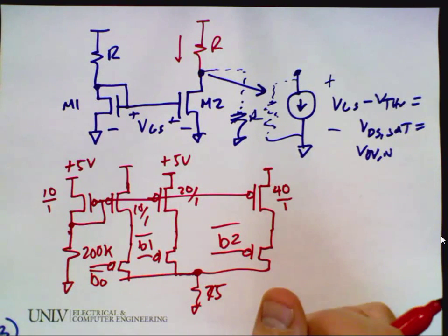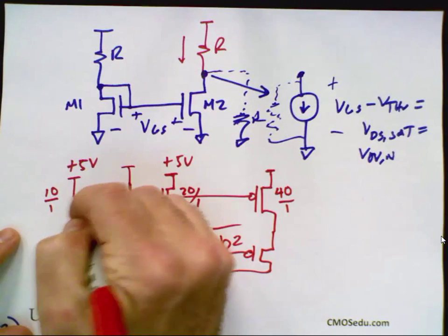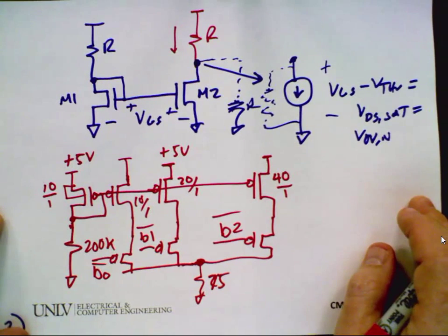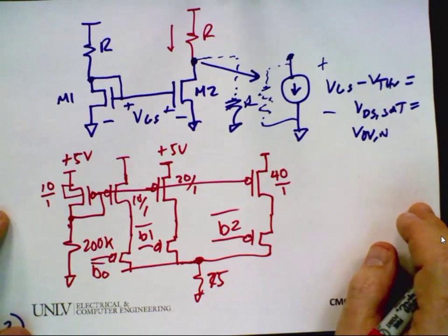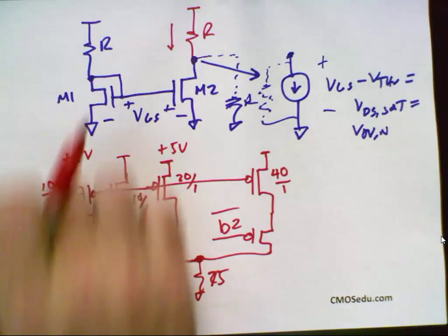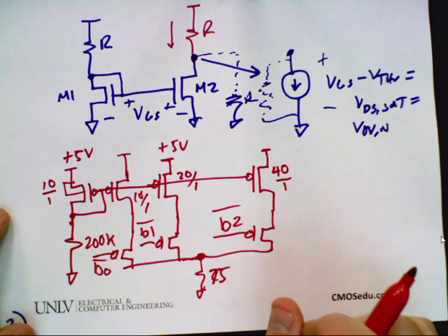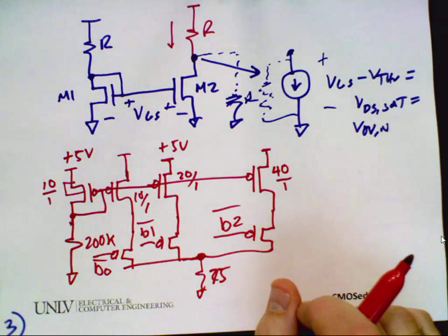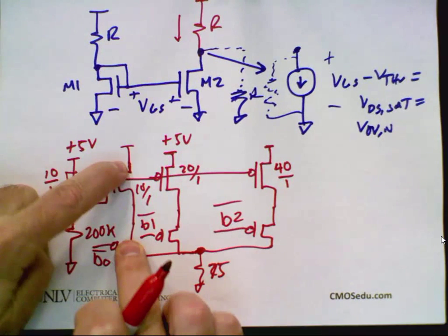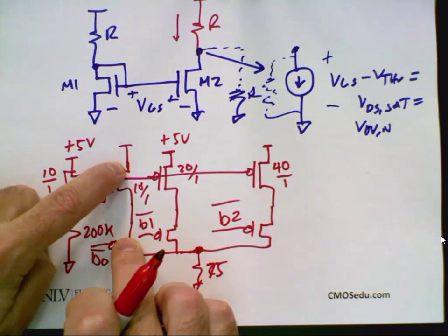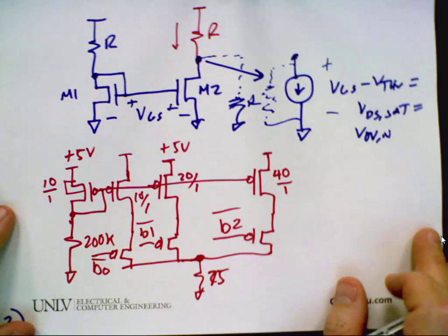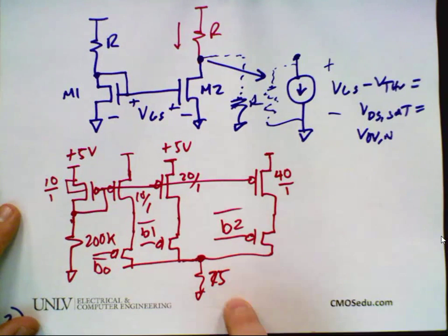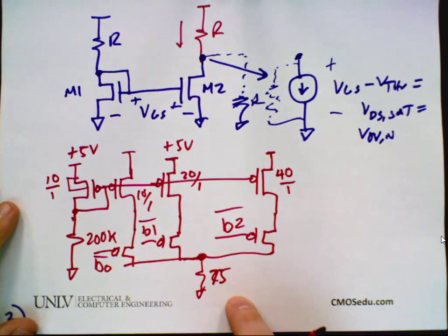Output resistance. There's no body effect here because the body is tied. They're all sitting in the same n-well. Source and body are shorted together. Okay, so once I calculate this current, then I know what the other currents are. And I know what the LSB is of the DAC. What's the LSB? Least significant bit, and it's this current, right? And if I want it in terms of voltage, what's the least significant bit? This current times 75 ohms. Challenging.